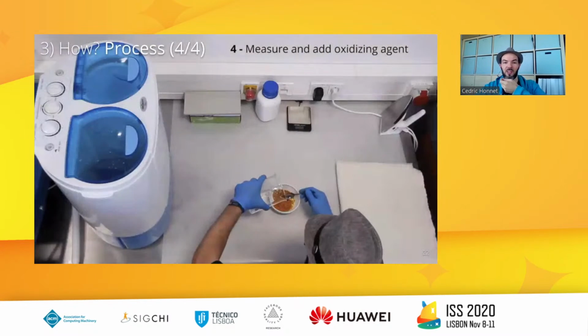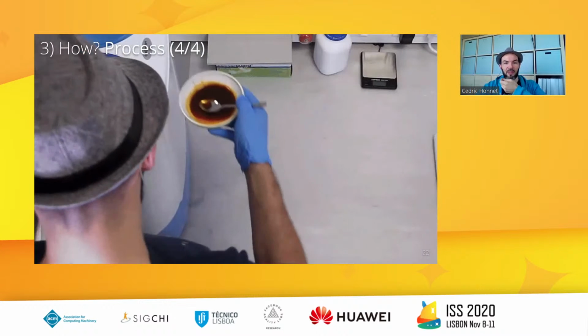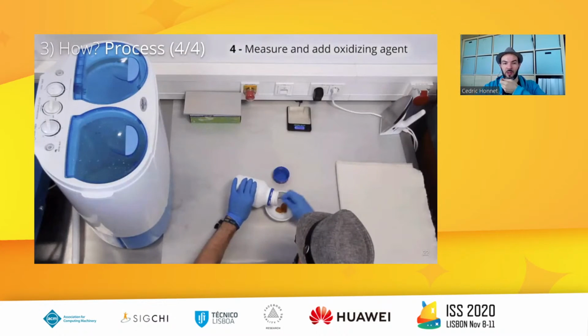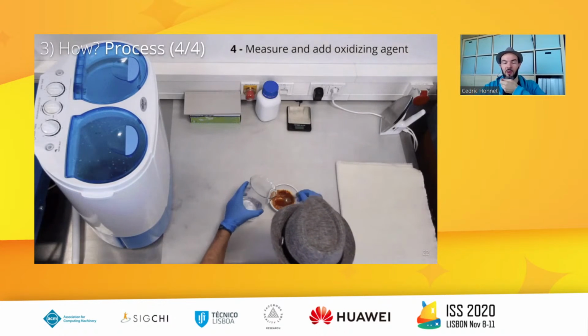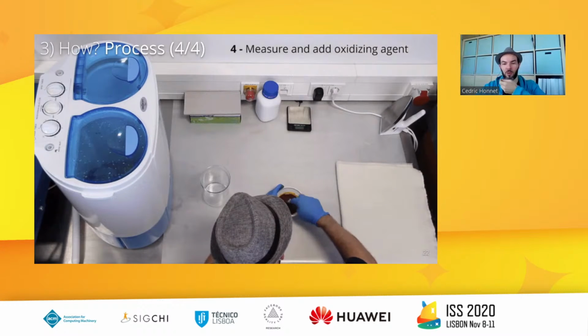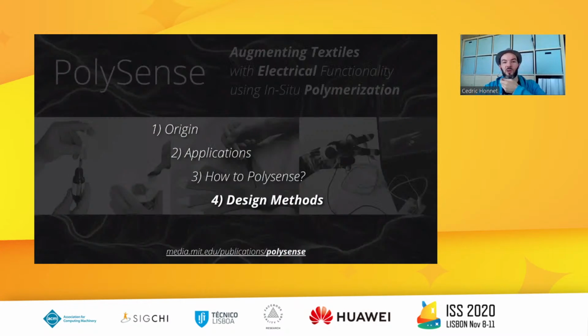Finally, add the oxidizing agent. Again, it's iron chloride. That's what triggers the in situ polymerization. For piezoresistive sensors, keep for about half an hour, and for capacitive sensors, maybe 2 hours at least. Okay, let's talk about some design methods now.